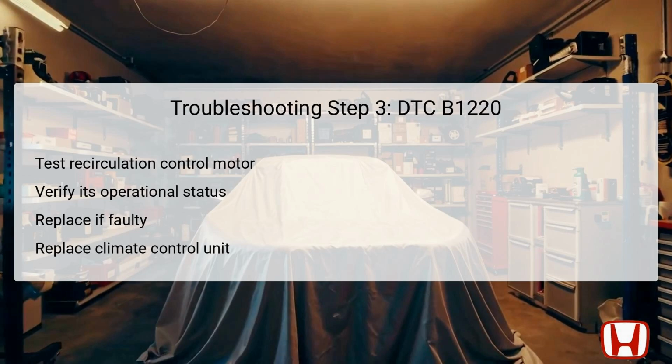On the contrary, if the recirculation control motor is found to be faulty during the test, it must be replaced to restore the vehicle's HVAC system capabilities. This step is critical, as both the motor and climate control unit significantly influence air circulation and interior comfort. While completing this testing, always follow the specific guidelines in the service manual to guarantee precision in diagnosis and